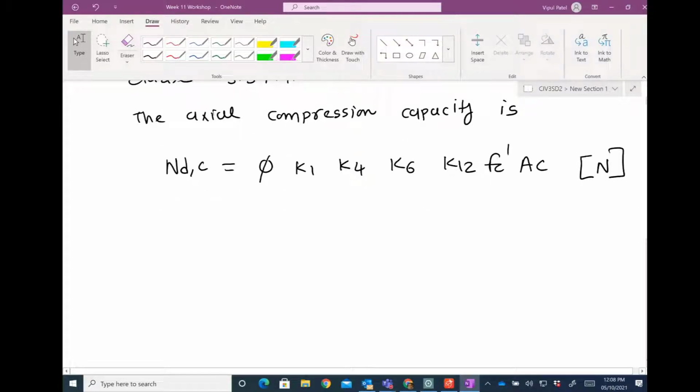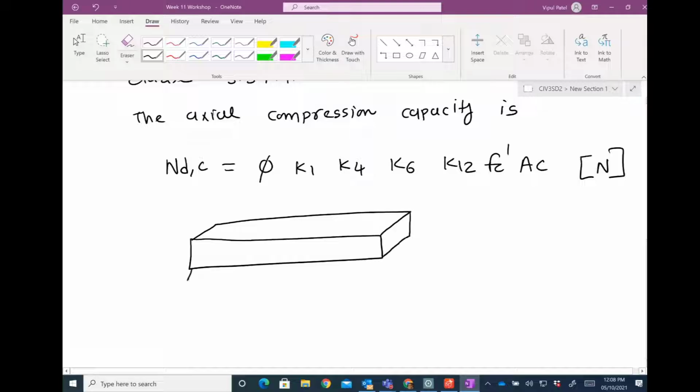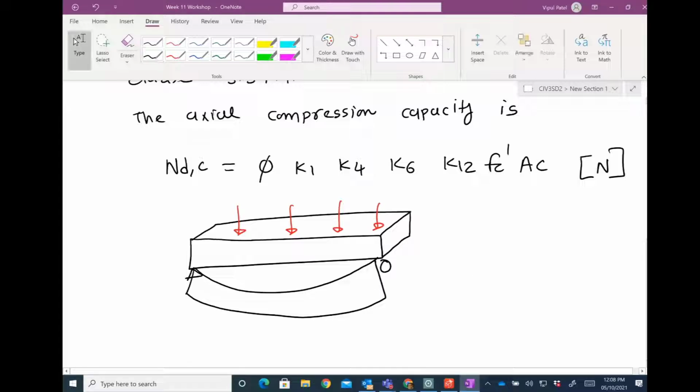Now if you really don't know these equations and your standard is not there, and you are sitting with the architects and you just want a 30-second go at finding the capacity of these timber members, it is quite simple. As you know, when you have a timber beam under bending, like I am revising from our lecture notes, you put a loading on the timber, and under these loading conditions your timber is going to bend in that fashion. Bending means that this part is under compression and this part is under tension, with a neutral axis dividing the compression part and the tension part.